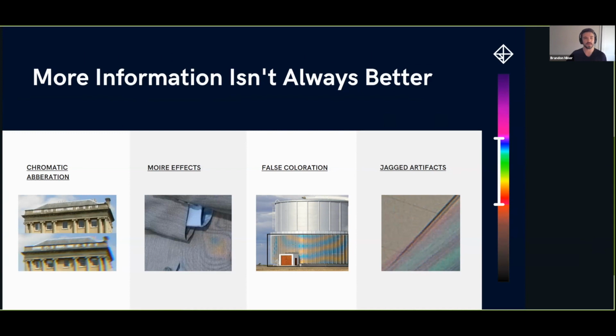So yeah, one other thing I want to mention is that when you take a picture in RAW format using an SLR camera, it's always in some sort of a Bayer pattern. You can get the raw Bayer pattern out. And if you actually want to understand what algorithm is being used, simple interpolation doesn't produce very good results. So there's a lot of things that go on once you get the information out of the camera sensor.